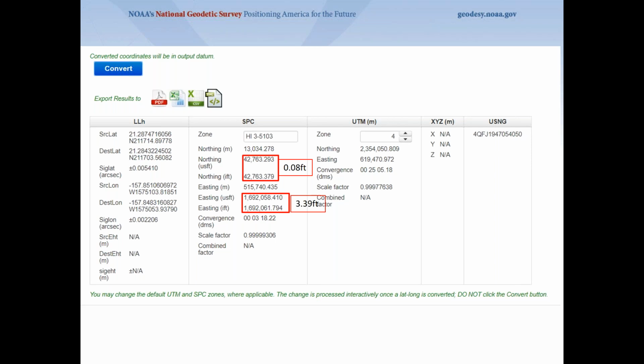So I told them, take the GIS back, convert everything to meters and bring it back to survey feet. And when they did that, everything matched up. You could imagine if they hadn't done that, we would have had striping on the runway that could be off by 3 feet or 4, almost 3.5 feet, and that could be disastrous for the planes.